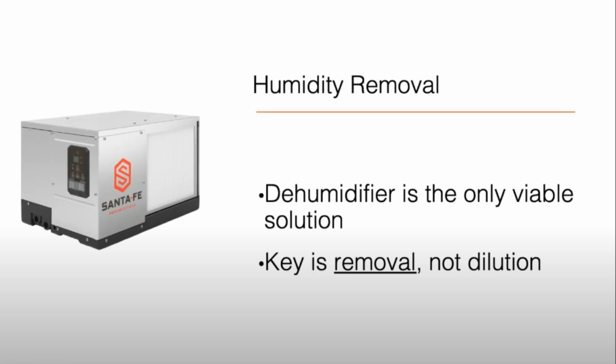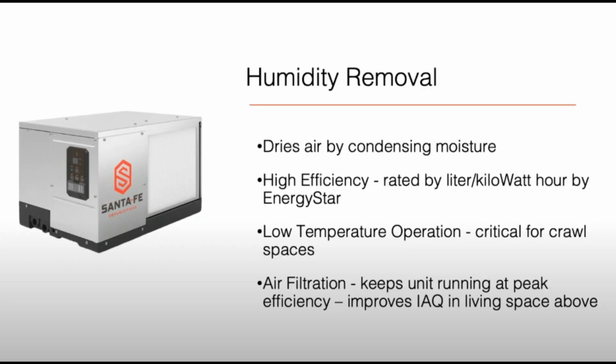Another important point pertaining to energy efficiency is the fact that expecting our air conditioning systems to condition the crawl spaces of homes is counterproductive to the whole push for energy-efficient homes. It's very possible that those other forms of conditioning a crawl space may go away as the code is updated. With humidity removal, the dehumidifier dries moisture by getting it out of the space.